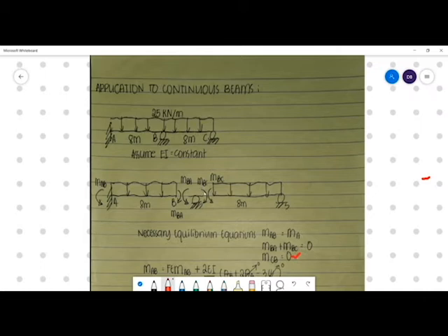And then our MBC, we assume counterclockwise. These are just all assumed directions. The assumed counterclockwise MBC will become clockwise with respect to the support. So another equilibrium equation is MBA plus MBC is equal to 0. Next, because point A is a fixed support, we know that MAB is also equal to the moment at A.